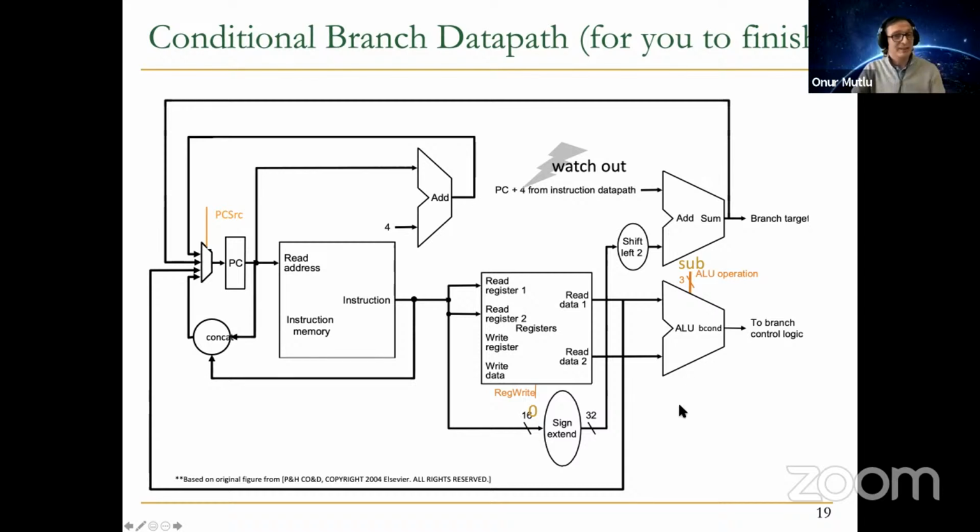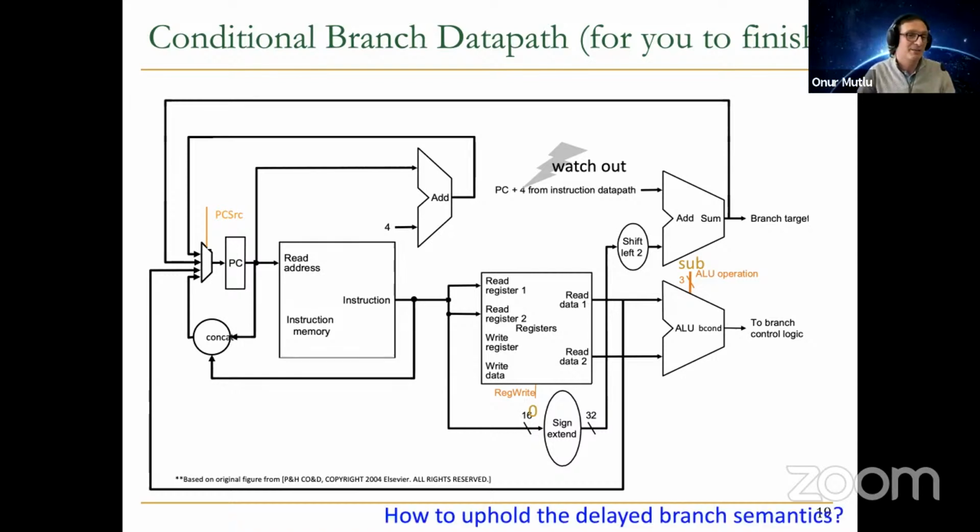Okay. So later, when we talk about multi-cycle architectures, we will see that you don't actually need this many adders, because we can do things over multiple cycles. Here, we have to do everything in a single cycle, right? We need to calculate PC plus 4. We need to add to it a sign extended immediate. And at the same time, we need to calculate the branch condition to determine what the next PC should be. And we have only a single cycle to do that. We basically cannot break this down into multiple cycles. As a result, we have this complexity added, and we will discuss that.